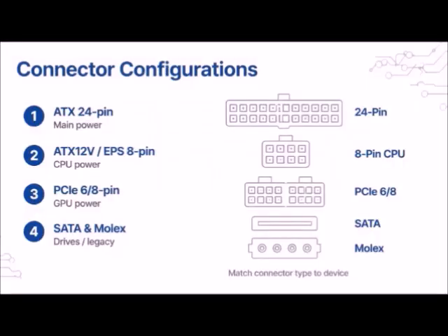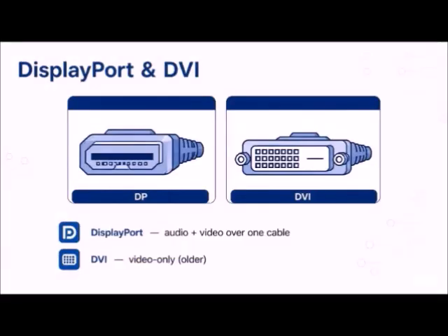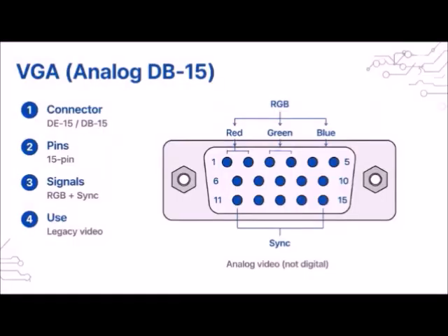Video and storage formats. High-definition multimedia interface, HDMI, carries digital video and multi-channel audio on an active 19-pin layout. DisplayPort is an open digital standard utilizing packetized data streams. DVI options include DVI-D, digital signals only, DVI-A, analog only, and DVI-I, integrated analog/digital. VGA uses an analog DB15 configuration.